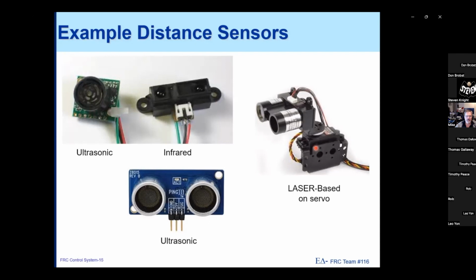The thing that you have to be aware of is that in the case of ultrasonics, the signals tend to spread out pretty quickly. Similar thing for the infrared sensor, whereas the laser is a point at some distance. So one of the problems that you have with these laser-based rangefinders is that they can be almost too accurate. So for instance, if you happen to be looking at a door and the laser pulse goes through the door and hits the back wall, then you're actually measuring the distance to the back wall rather than the distance to the door. So the ultrasonic would be not as accurate.